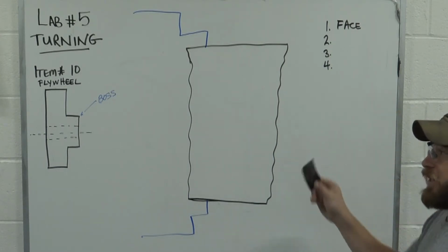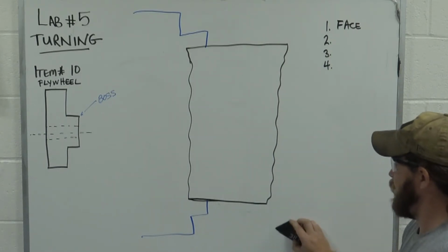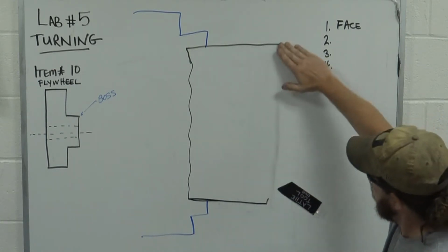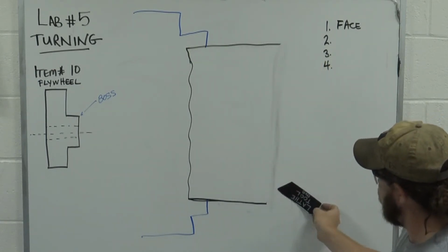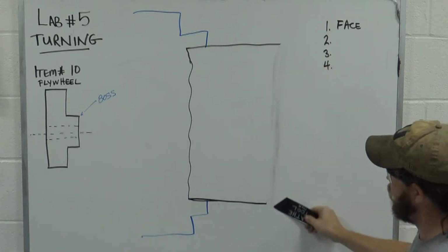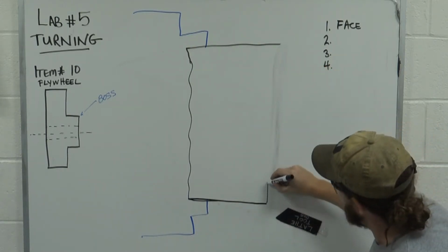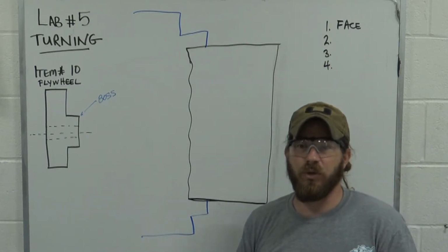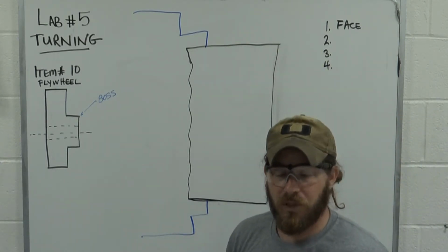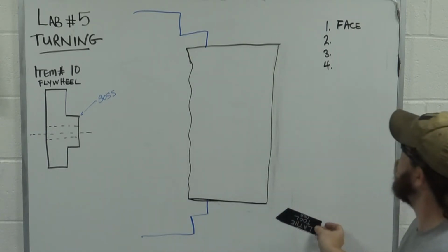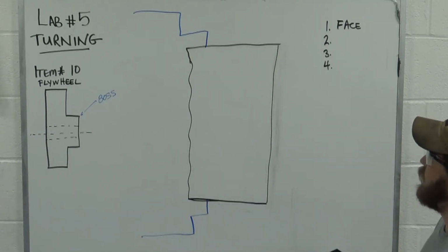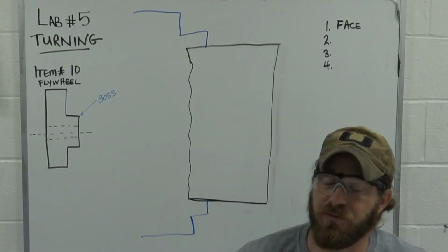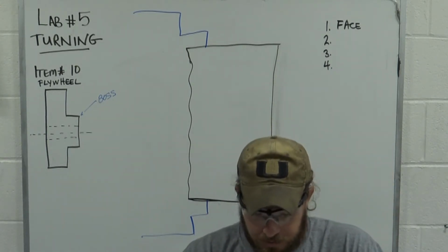So we'll take our lathe tool and we'll just face enough off, like this. Now we have a nice, smooth, clean edge. So that's our first step. Again, that will almost always be your first step in every lathe process.